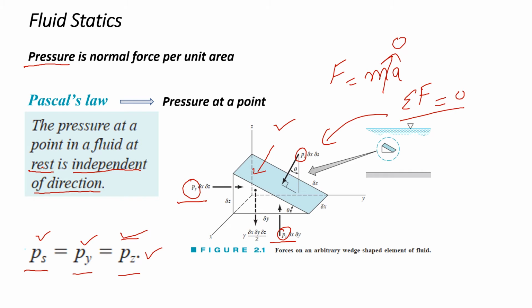So this was our first analysis that we did on a fluid element that was at rest, and we summed all the forces that were being applied on that fluid element, and then we came up with Pascal's law, that is, the pressure at a point in a fluid is independent of direction, given that the fluid is at rest.